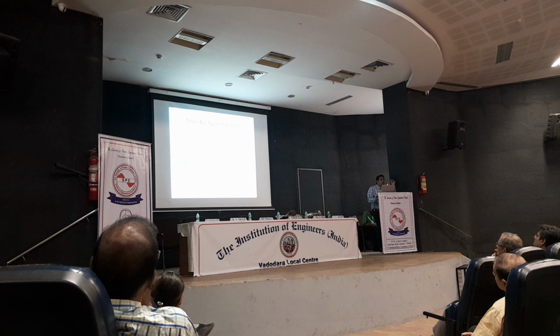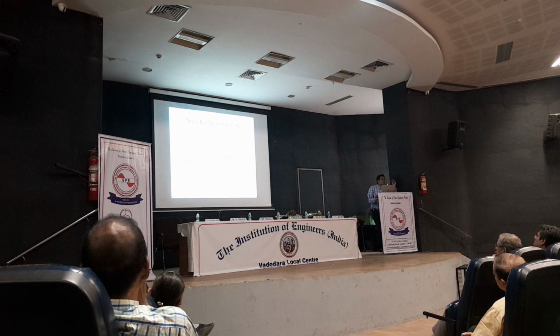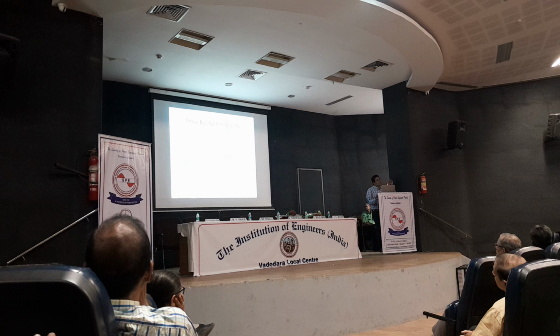Now, whenever you are going to do it the first time, the difficulty you will feel is that many times when you go in run mode, these pie charts are not coming by default. When you see it in edit mode, this pie gauge will be there, pie charts will be there. But when you go in run mode, it will not be there. So you have to modify some settings of the pie chart so that it will be visible.